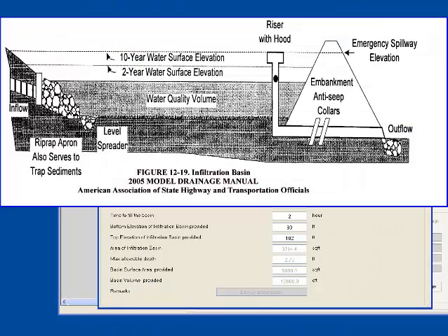Quantity control for infiltration basins is performed similar to extended detention ponds. They are designed to reduce the peak flow from 2-year and 10-year storms for channel protection, and pass 100-year storms safely. It is preferable to locate an ED pond, as a part of a hybrid system in the treatment drain, where the infiltration basin feeds to the extended detention storage facility.